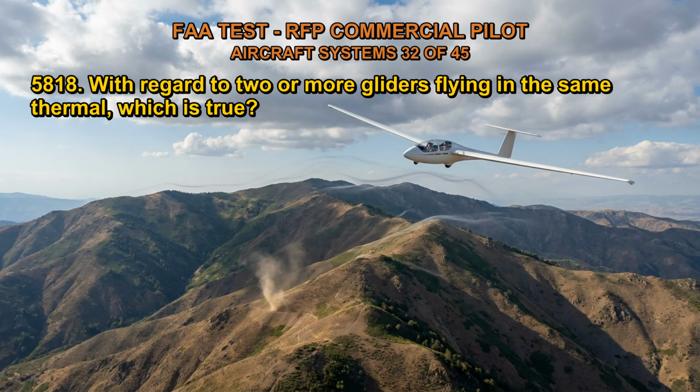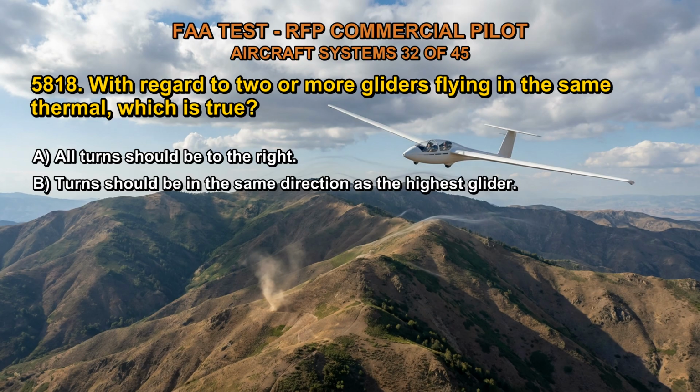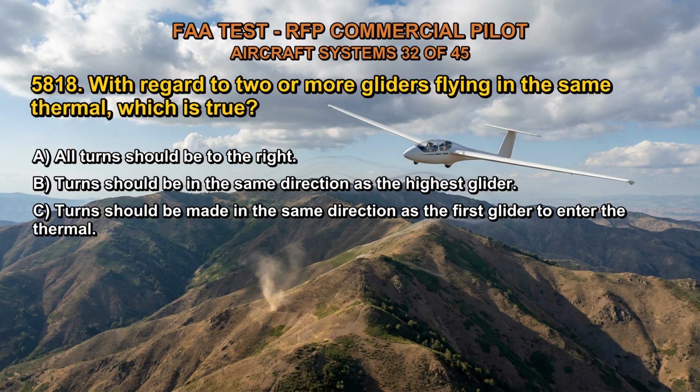5818. With regard to two or more gliders flying in the same thermal, which is true? A. All turns should be to the right. B. Turns should be in the same direction as the highest glider. C. Turns should be made in the same direction as the first glider to enter the thermal. The correct answer is C.